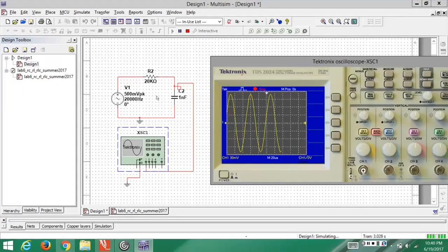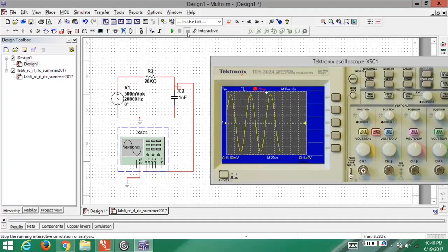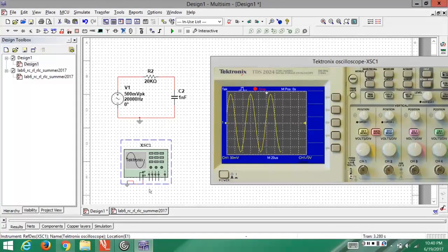But when it comes to this resistor R2 and we do the same kind of setting, that is, we connect channel 1 from here, this voltage reading taken at this point is basically the same as taking the voltage reading across the power supply, because the voltage drop here is going to be the same as the voltage reading for the power supply source.